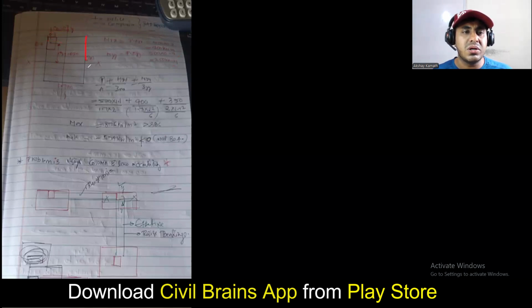So if this is 2 meter, half of this is 1 meter. If this is 1 meter, and if this column dimension is 0.4, half of that is 0.2. So 1 minus 0.2 will be 0.8. So this becomes 0.8 here. In the same way, here also it is 1.7. Half of 1.7 is how much? 1.7 divided by 2 is 0.85.